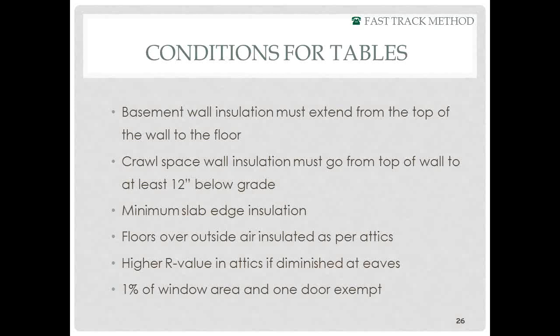There's also a couple of options on floor insulation. If you have floors that are over unconditioned spaces, like a tuck-under garage, the packages will give you an R value that floor needs to be. If you build a floor section that is completely over outside air, then you have to insulate that floor. If you're using the packages, you have to insulate that floor to the level that's given for the attics.